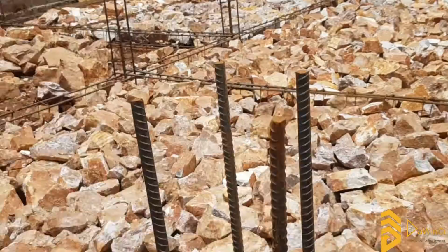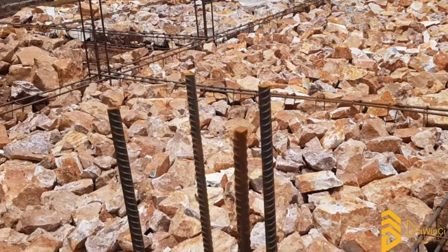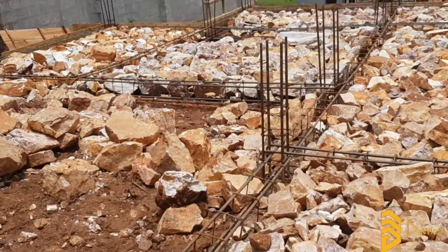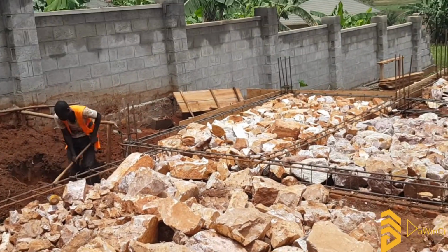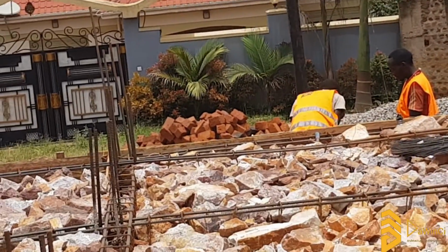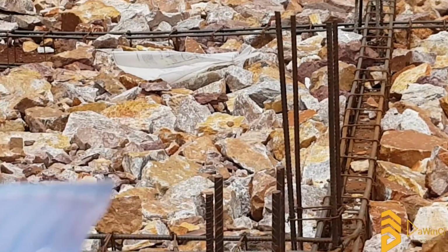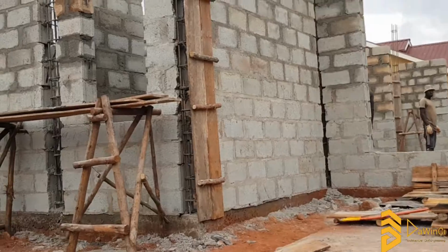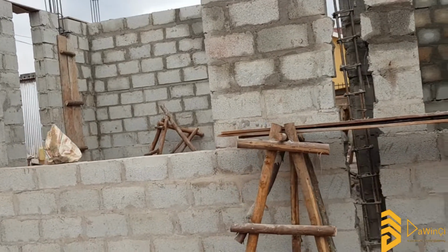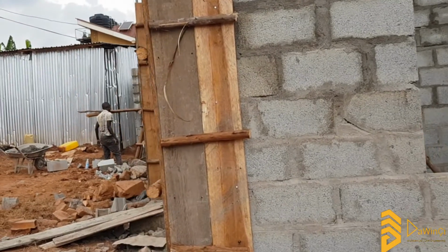Then the other reason why we do hardcore is because hardcore creates that strong base where the slab is going to sit. So if you have unstable soils that are probably expansive, or soils where you've done a lot of backfilling and the compaction is not really as sufficient, that hardcore actually helps to create a strong ground on which the slab can sit. Remember, the ground slab is an unreinforced slab, which means there are no iron bars in that slab. It is purely plain cement concrete. So when we are having that slab, we need to make sure it is sitting on a very strong ground where it cannot easily just buckle or sink in along the lifetime of the building.